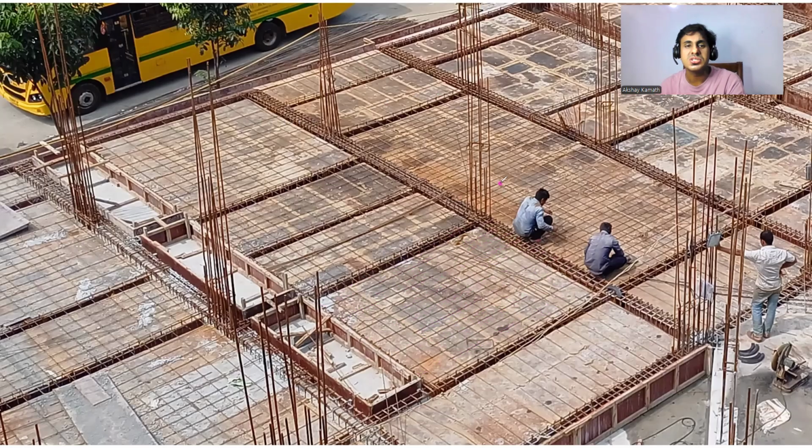If you go to the construction site and I ask you to draw the bending moment diagram, the first thing that should come to your mind is how you're supposed to draw it. Let me put it here. Let's say I take this. I'll have a negative bending moment here, then it will be sagging. Since it's a continuous portion, I'll have negative, sagging, negative, sagging, negative, sagging, negative, sagging. This is how the bending moment will be. Based on that only we are putting the reinforcement.